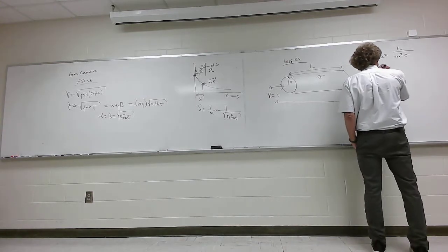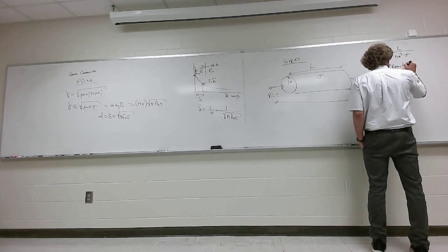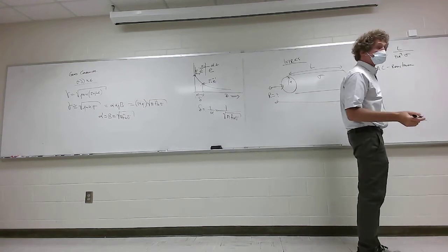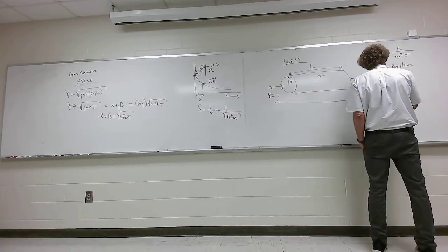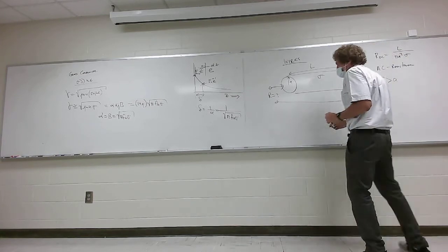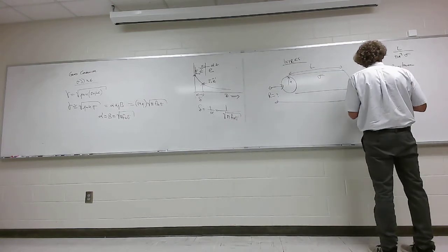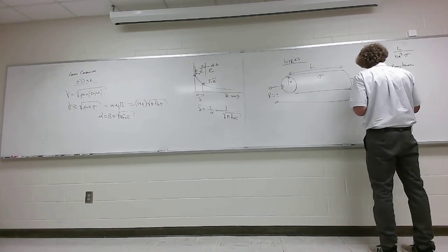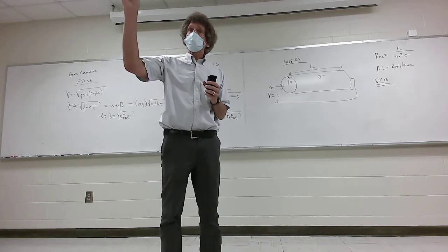When I talk about AC resistance, well, at low frequencies, it's that. But whenever the skin depth is actually, sorry, I got this wrong. When the skin depth is less than the radius of the wire, now think about it. Now the electric field can't penetrate into the wire.